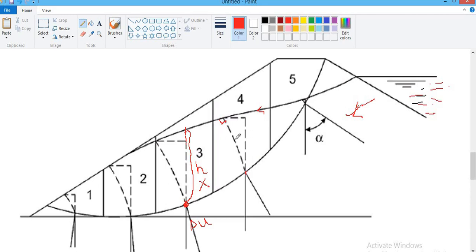If we follow an equipotential, the term equipotential means that along this line, pressure head plus elevation head is the same. That means total head is the same. Total head is equal to pressure head plus elevation head. So this is an equipotential, and this is a flow line and an equipotential. Therefore, along this line, these two are constant.